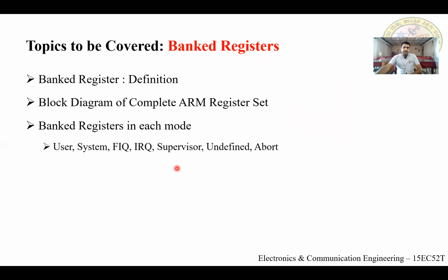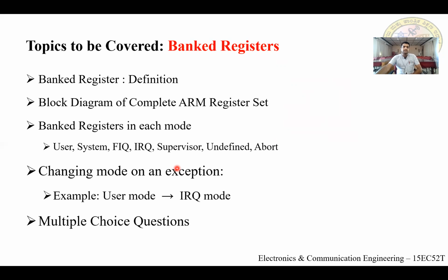We will discuss how many banked registers are available in each mode. Next, with one example, changing the mode from user mode to IRQ mode, we will discuss the steps and which registers are affected. After that, we will see multiple choice questions on banked registers.